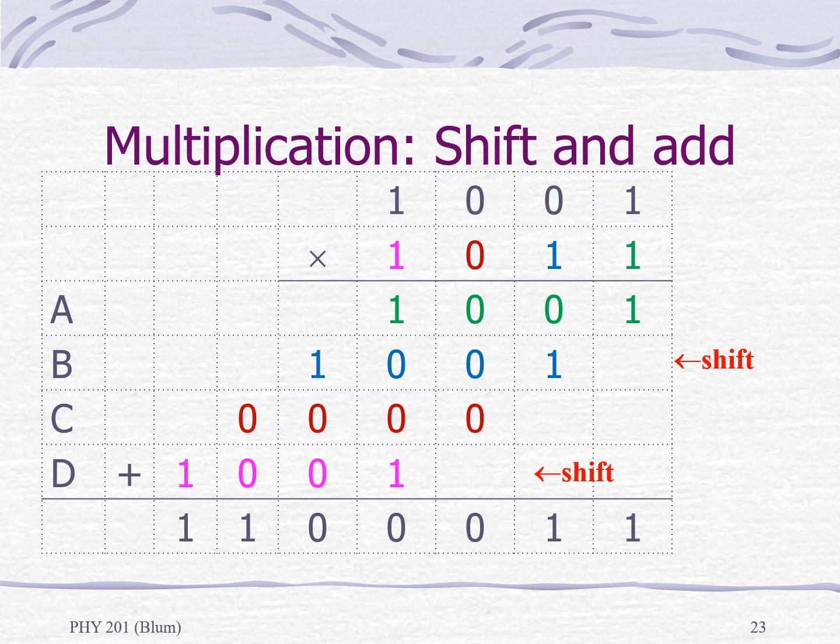Multiplying by 0 gives me 0. So in row C, I just have a bunch of zeros. And then finally, 1001 times the 1 in the eights place gives me that answer, that 1001 in row D that has been shifted 3 times. So we are shifting and adding. Multiplication in binary is just a combination of shifting and adding.